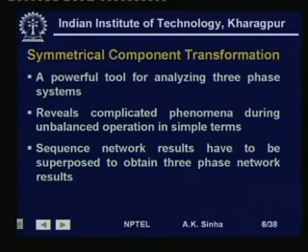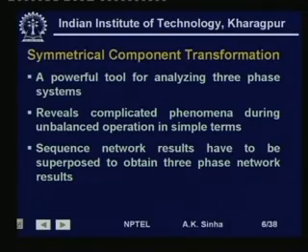Because of this particular property, it is a very powerful tool for analyzing three-phase systems. It makes the analysis much simpler to do. Another advantage is that it reveals the complicated phenomena during unbalanced operation in simple terms, that is, in terms of sequence currents and voltages, and we can understand the unbalanced phenomena in very simple terms of these sequence currents and voltages.